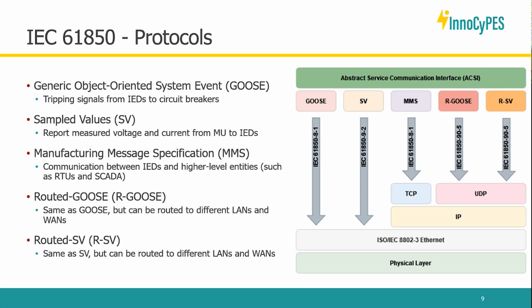The third point, you mentioned using encryption or authentication to prevent injection of messages or this kind of attack. The issue is that in operational technology, specifically in digital substations, we need these measurements to be sent, received, and then processed by the protection algorithms in less than 3 milliseconds from when the measurement has been done. Given that we need a latency lower than 3 milliseconds, and we are publishing one new sample value every 100 microseconds.